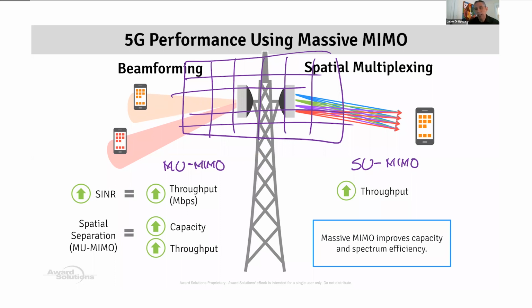However, in frequency range 2, frequencies of operation above 7 gigahertz, in particular, my 28 or 27 and my 39 gigahertz band, M261, M260, in those cases, the frequency of operation is really large and there's only line of sight. That is, in order for your 5G service, my mobile phone, this one, has to be pointing to the antenna, right? There has to be line of sight, otherwise I don't get coverage.